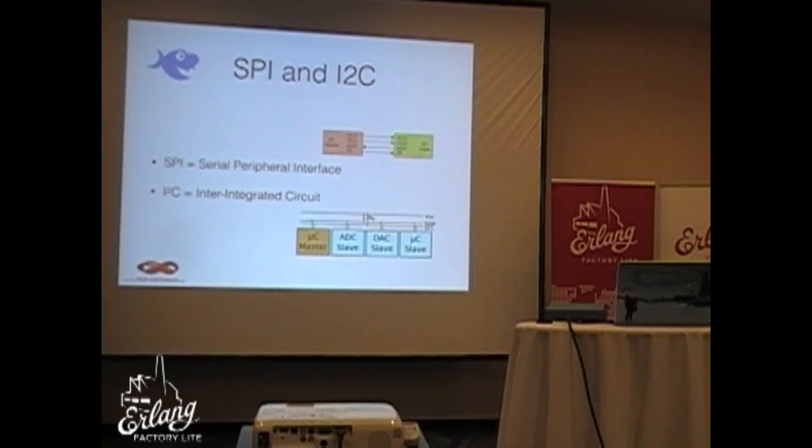The good thing about this one is that it has addressable clients, so you can send data packets to one of the clients or one of the slaves on this line, and they will be able to pick it out from the wire, basically. And all of this is usually for board local stuff, like stuff that's close to the hardware board, because reliability over longer distances is not so good if you have disruption on the line or noise on the line and stuff like this.